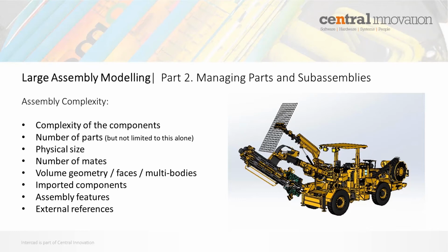One other thing to watch out for with imported components is their image quality. Similar to our parts, sometimes those imported components that can be downloaded from external websites will have their image quality cranked up to make them look a little bit nicer when they appear on your screen. Assembly features like assembly cuts can also impact performance, especially if there's lots of them, and that's because they're inserted into the Feature Manager design tree after the mates folder.